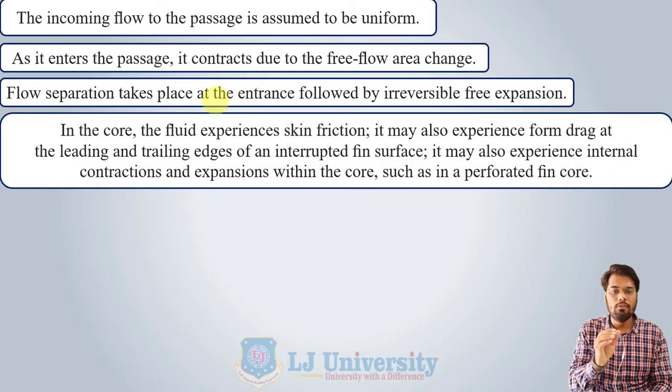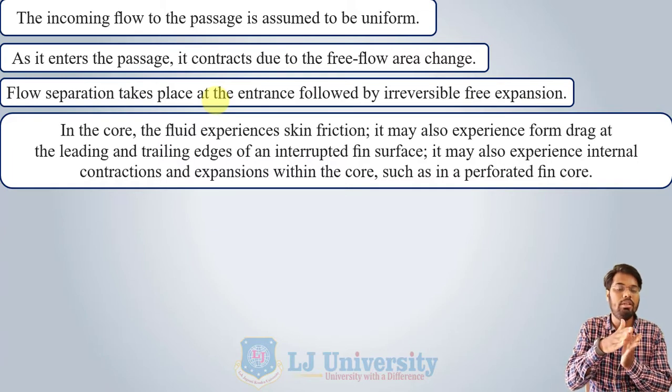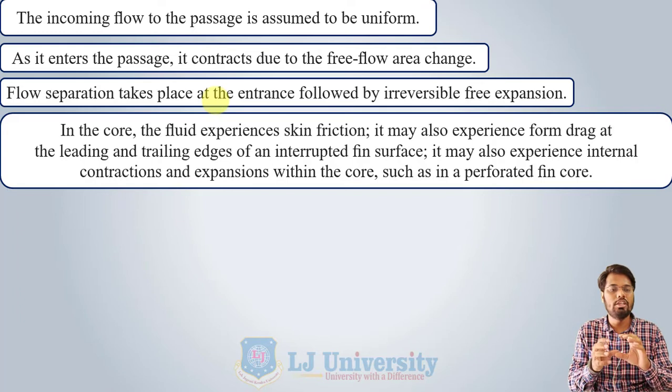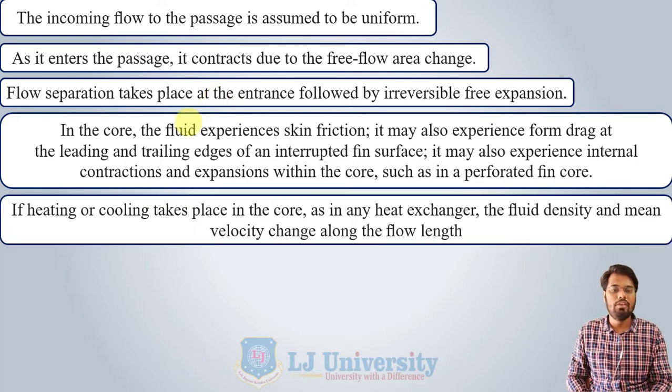In the core, the fluid experiences skin friction due to the contact with the plates. So the fluid experiences skin friction. It may also experience drag at the leading and trailing edges of interrupted fin surfaces. It may also experience internal contraction and expansion within the core, as we have discussed in the figure.